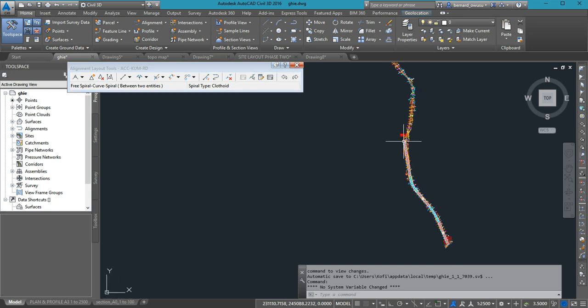So that will end the alignment design. The next thing we want to do is to do the profile. Very simple. It's almost like the alignment design. Please, any problem, any question? I'm saying make sure that you have an alignment of at least 1 kilometer. Is yours up to 1 kilometer? Check the end chainage. What's your last chainage? Oh, more than enough. What's your last chainage? At the back. 1 point, good. That's 1 plus something, more than enough.